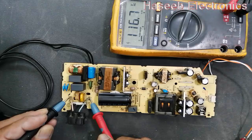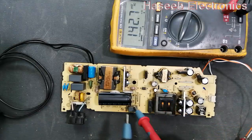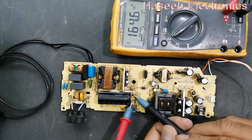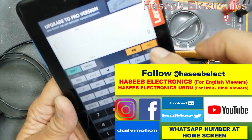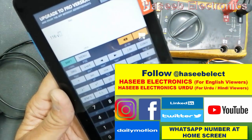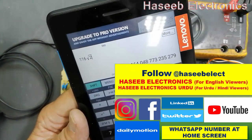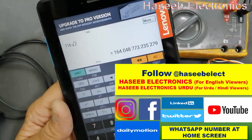I applied 116 volts at input, and I am receiving 164 volts. 116 times square root 2 should be 164 volts, the peak voltage at the capacitor.